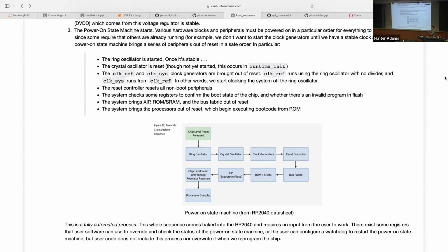The VGA screens, for instance. Right? In order to drive those VGA screens, we need to update the pixels at exactly 25 megahertz. It'd be very hard to make guarantees like that with this ring oscillator. Right? But if you're just running some internal thing, then that's perhaps worth knowing about, particularly for really low power applications.